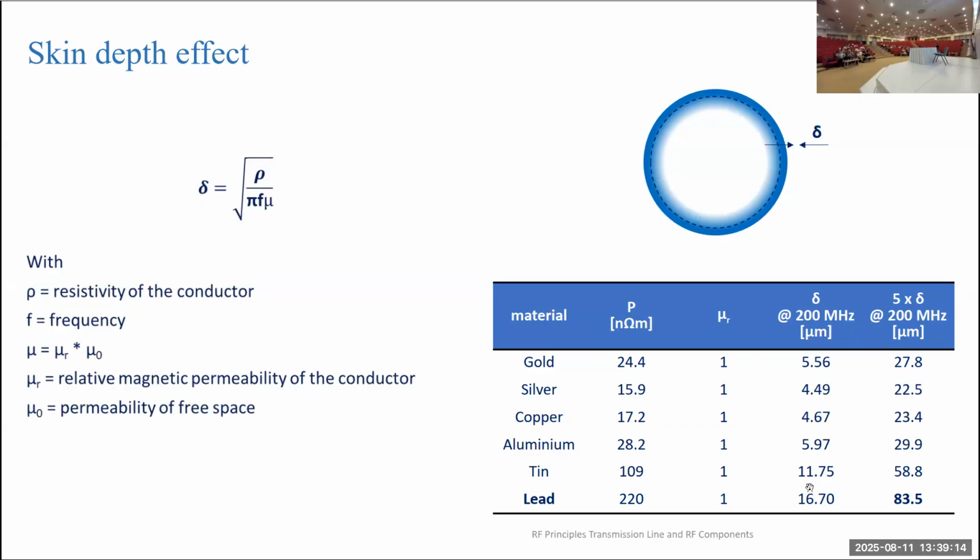And mostly copper is used. And sometimes copper is coated by this silver. And this layer may be 5 to 10 micron, because for high frequencies, skin depth is very small. And if you are at 3 gigahertz, 1.2 micron is the skin depth.